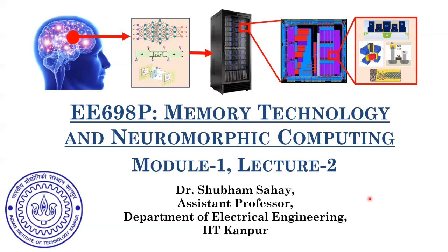Now, immediately close to your processing core, you also have another hierarchical level of memory, which is known as cache memory. We discussed that there are 3 levels of cache: L1 cache, L2 cache, and L3 cache. We saw how L1 and L2 cache are composed of a content addressable memory followed by an SRAM memory array, right?